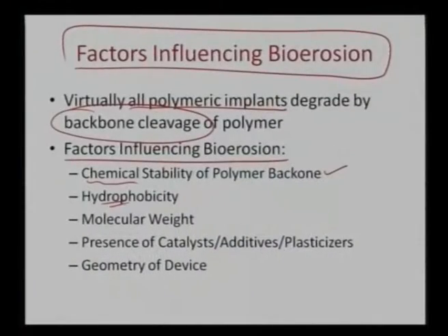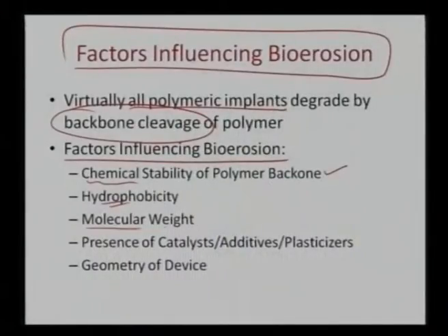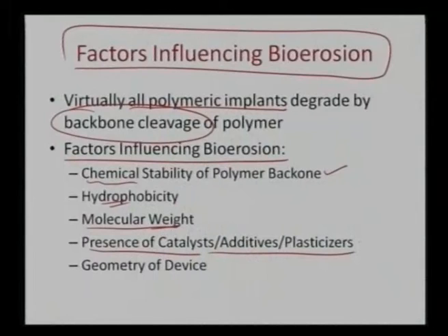It can also be affected by the hydrophobicity. If the material is hydrophobic in nature, it won't allow much water uptake. It can also depend on the molecular weight. If the material has a very high molecular weight and much more cross linking, then obviously the overall degradation will be much slower. Again, there is the presence of catalysts, additives and plasticizers. Depending on the assistance it can get from catalysts, additives or plasticizers, the overall bioerosion rate can be controlled.